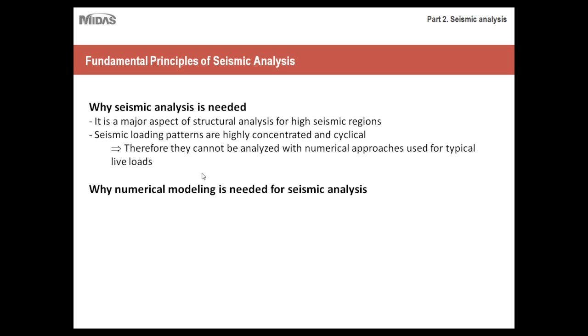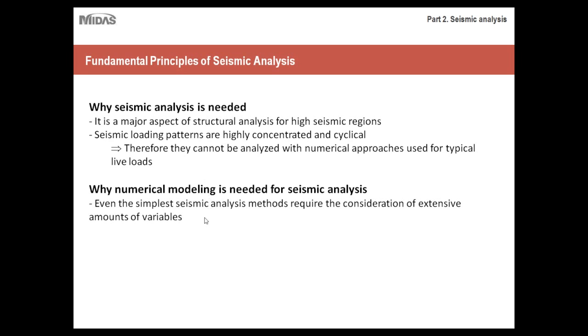Why is numerical modeling needed specifically for seismic analysis? Even the simplest seismic analysis methods require the consideration of extensive amounts of variables. As I said, because seismic analysis is time dependent, cyclical, and varies very sharply over a very short period of time, a large number of variables needs to be considered. That's why numerical modeling becomes especially effective, because it can take all those variables and run the calculations much more efficiently than is possible by hand with spreadsheets.